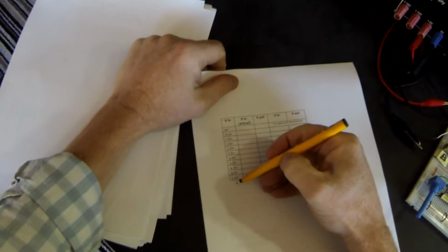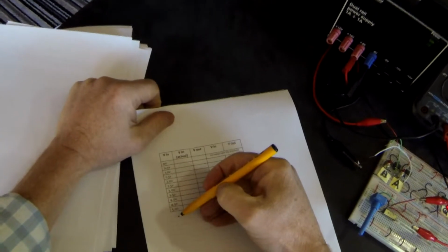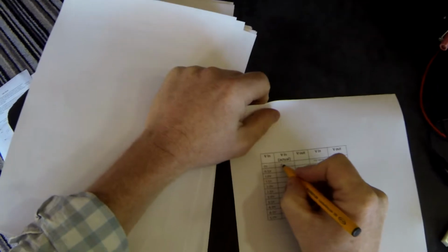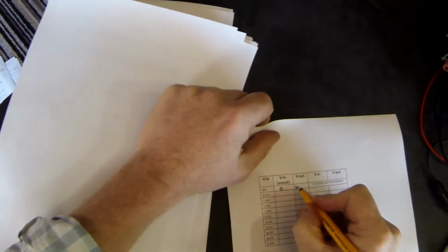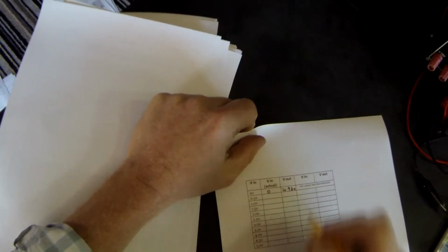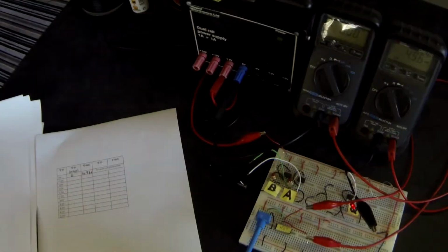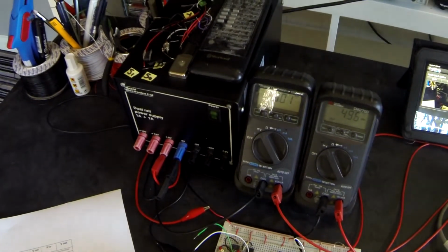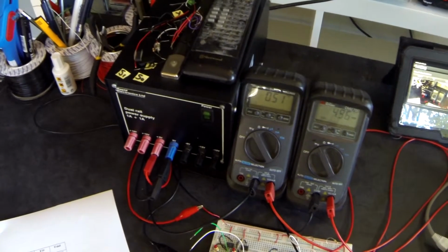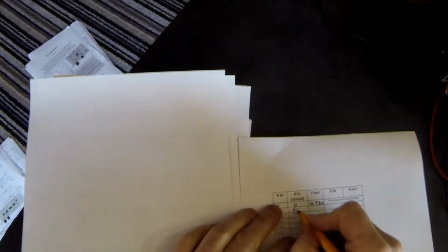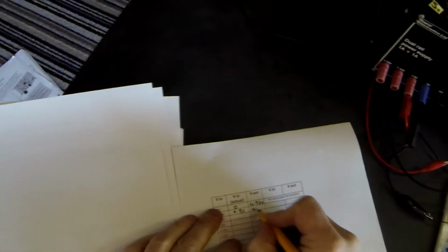So I'm going to write down that value to start. Now it doesn't matter if we can't get to exactly these values in the table, as long as we write them down as they are on our voltmeters. So at the moment I have 0 going in and V out is 4.96 volts. So now I'm going to go to 0.5 volts V in. So up I go. That's pretty close, 0.51, and my output is 4.96. You'll see that V out hasn't changed.